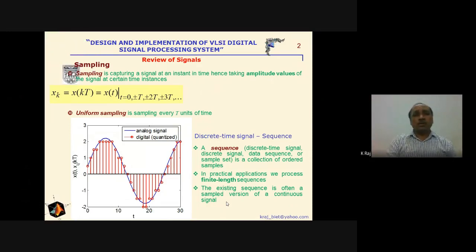Now, the continuous time signal is represented something like this, that is, it is a function of time. Here we have represented it as x of t, and say the nature of the signal is sinusoidal with some DC level at the start. So if this signal is blue in color, the signal is continuous in time, changing its value with respect to time, and the nature of the change is sinusoidal. Now we can say this signal's variation is analogous to the physical quantity. That's why this is also named as the analog signal.